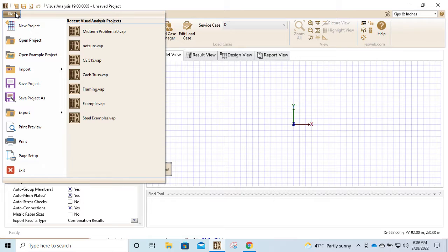You can in VA, right? The problem is in Revit, I don't know if you guys are familiar, there's the physical model in Revit, and then there's the analytical model in Revit. And you can have it show you what they call the analytical model, which is Autodesk trying to bridge the gap between modeling something and actually analyzing something. And at some point, I can imagine, they've already tried, making it an ability to actually do a finite element analysis of your structure in Revit. And so there's little line elements with nodes, okay, and those nodes can be oriented all over the place.